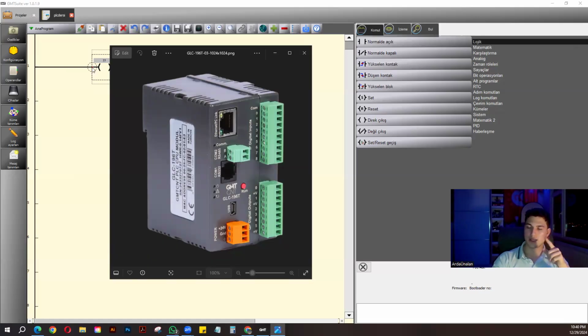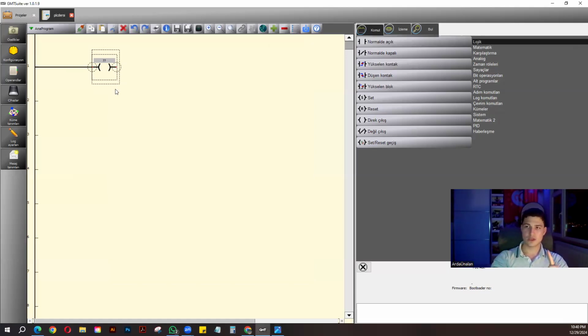I'll just tell the program to make it a 1 instead of 0, and in the PLC it will turn into something like that. If I connect any cable to the 1, 24 volts will come out from the 1, so I'll get the voltage I want from the output that I want. We can also use them as virtual relays, in the relay system. So the output system is like that.